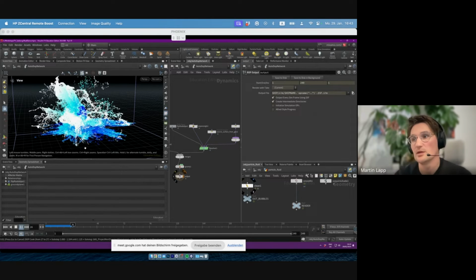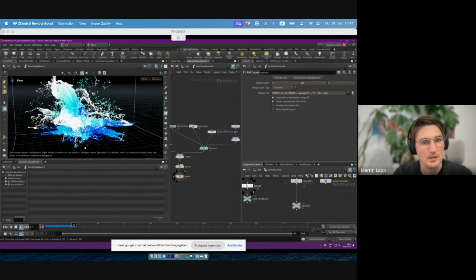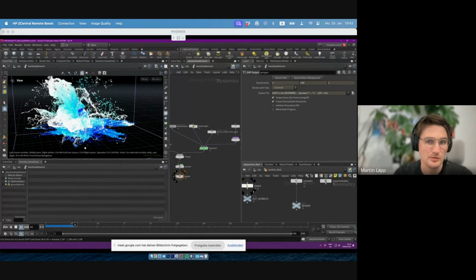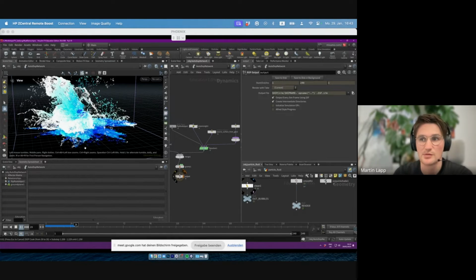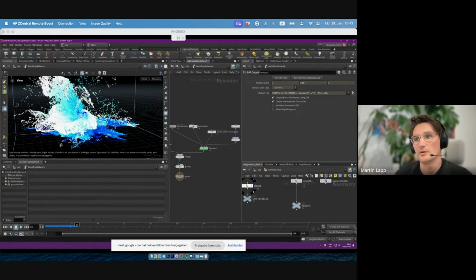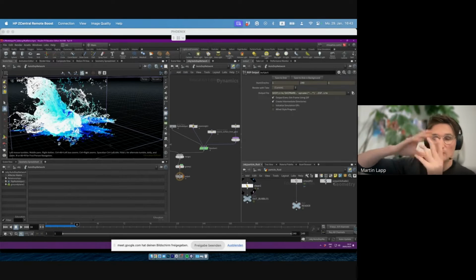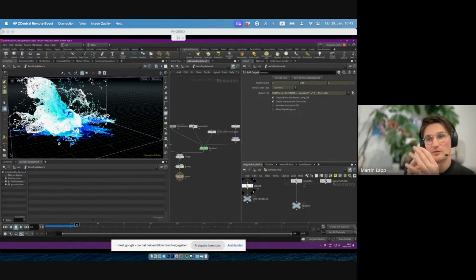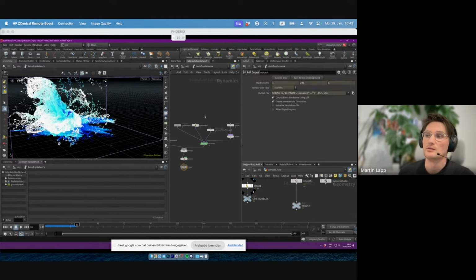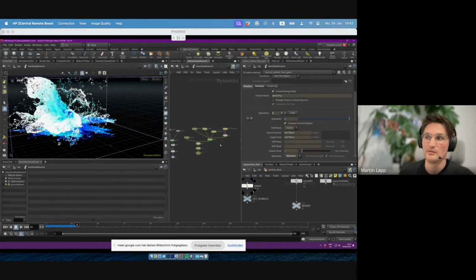So yeah, that's actually a good saying. If your source is great, then you don't have to do much in your simulation. Basically, the blobby guy or the noised up sphere that we have here, or whatever it is in Houdini, if you dial in your source correctly, and you spend most of your time dialing in your source and the velocities, how it reacts, then this setup gets very, very easy.